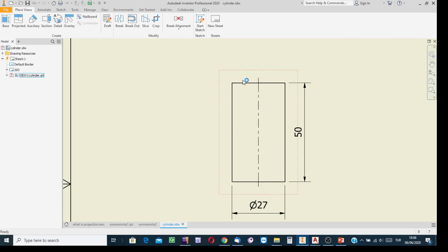If it were a conical object, then at this end the diameter would be shown, and at the opposite end the other diameter would have to be shown. Since there is only one diameter value for the description of the object, this means no doubt it is a cylinder.